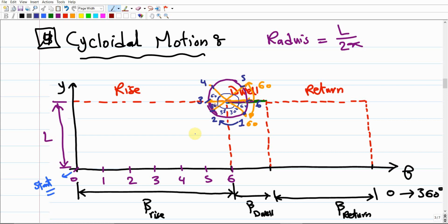Sorry, this is going to be also 60 degrees, okay? But this angle with the vertical axis is going to be 30, and this is going to be 30. So as I said, you just draw a horizontal line, measure 60 degrees down, measure another 60 degrees on the top, put 2 marks, and then draw a line at the 60 degrees to connect this mark to the center point and this mark to the center point. You're going to end up with 3 lines: the horizontal one and these 2 crossed lines, so you are in a good shape.